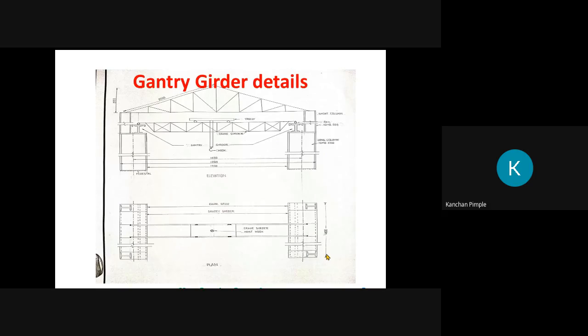Spacing of truss. In that we have to provide these two columns, and again we have to design this spacing on which the gantry girder rests. Is it clear? Any doubt how to draw this? And in this case, you have to show every part with scale. And here the gantry girder elevation is there. So, any questions?